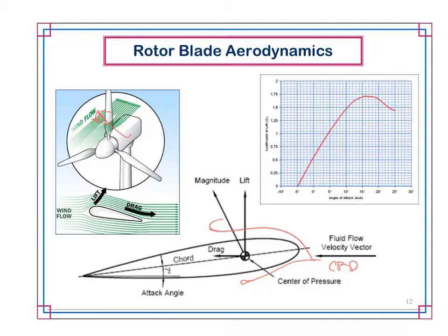Wind turbines are designed so that in their normal position, they have a maximum angle of attack to get maximum capture of wind, okay? So you're not adjusting the blade while it's at a low wind speed. You're only adjusting the blade when the wind speeds are too high. You actually want to shed some of the wind. You don't want to capture that much energy, because once you've exceeded the generator output, at that point you're not generating enough induced torque to slow the turbine down. So it's going to continue to speed up. So at that point, the only way to do it, as there's so much power in the wind, is to start to shed some of that energy so that you don't capture it, so you don't overload or overcapacity your generator.